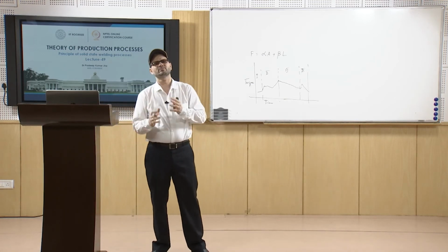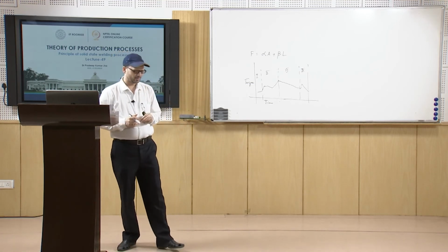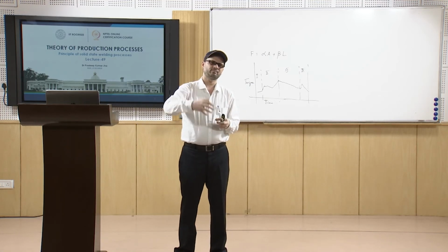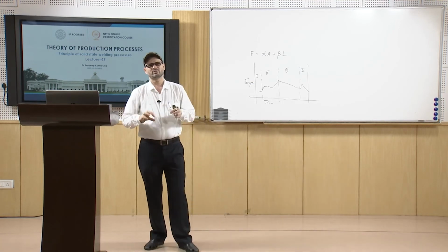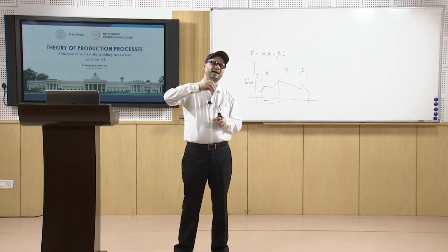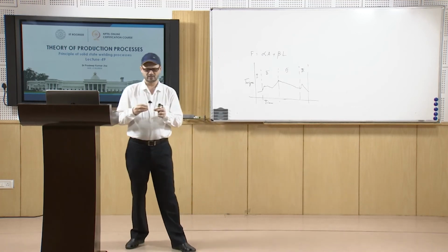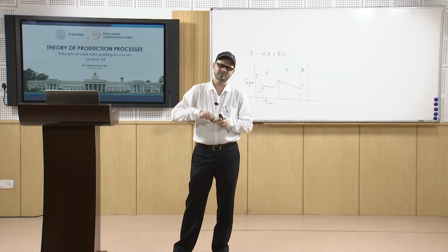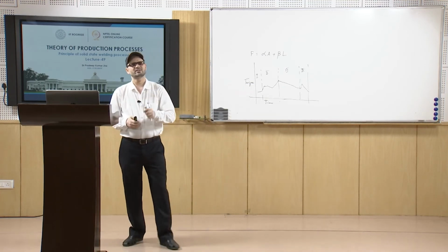So that concept is used for the inertia welding, and then you have the friction stir welding. In friction stir welding, there is a stirring action in the zone where the welding has to be carried out. You will have a tool, and that tool is going to rotate in the joint, and because of the plastic deformation and the shearing action, the bond will take place. So that is friction stir welding.